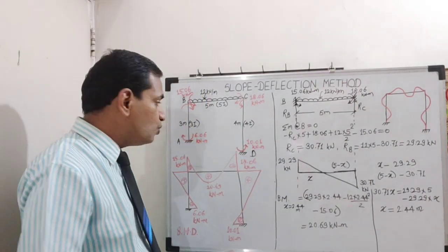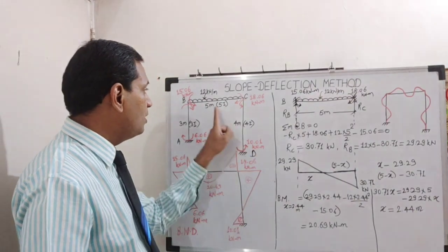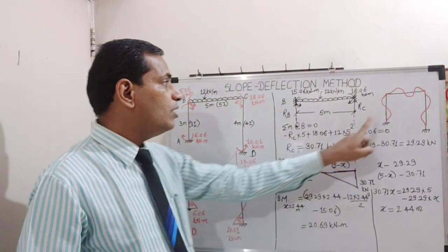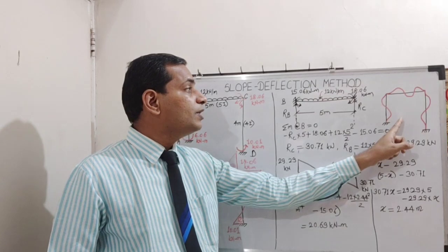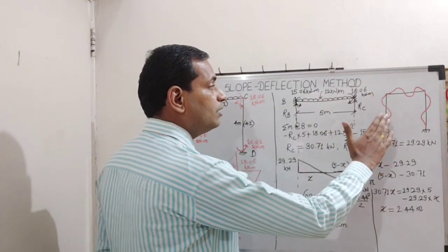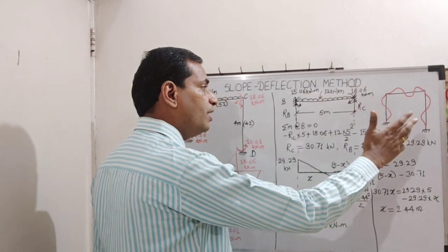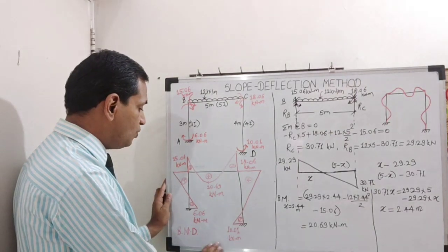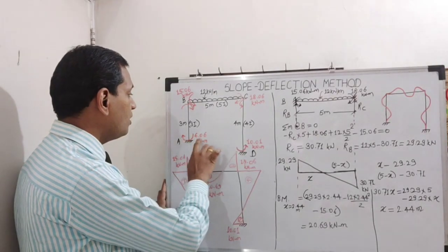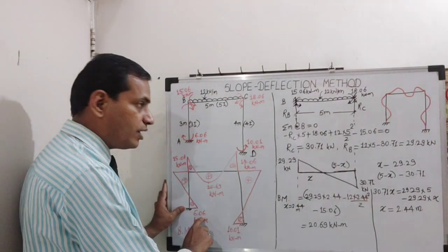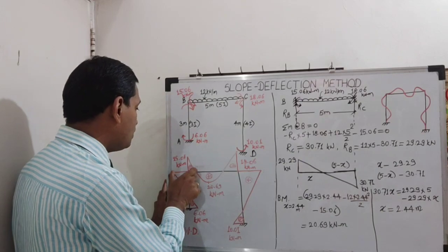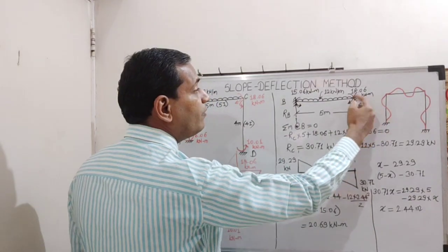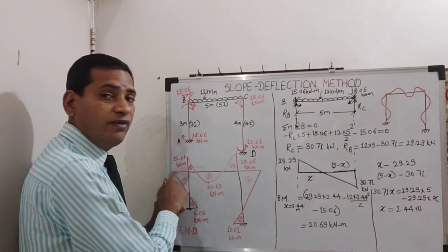Now, I have shown all these moments except this one here. Okay. So for this diagram, along with this moment, I have drawn now the deformed shape of the frame, and wherever the members deform on those particular sides, I have plotted bending moment ordinate values. So this is our BMD on tension side, 6.06 clockwise, deformation on right hand side of the column, hence value is on right hand side. 15.06, this value clockwise rotation or moment, deformation is on left hand side, so moment or value plotted on left hand side of the column.